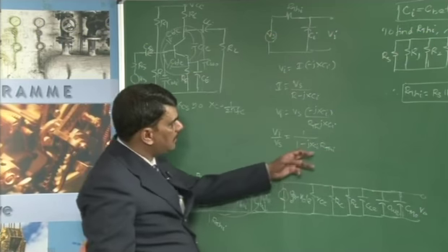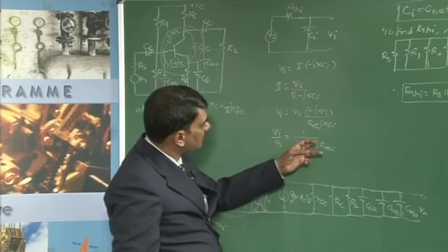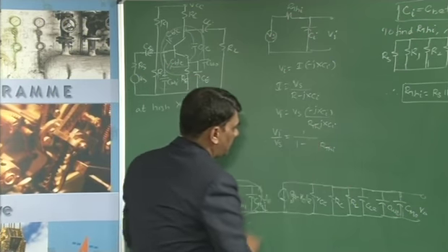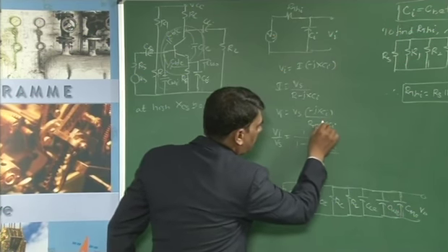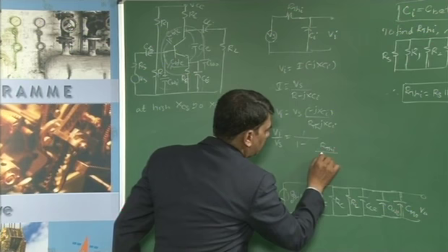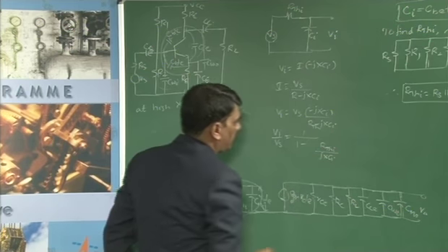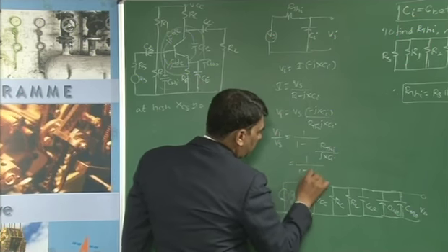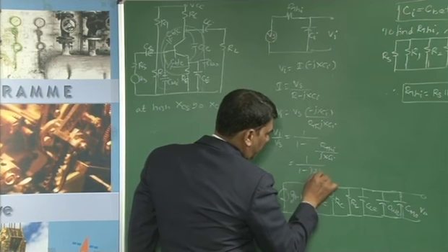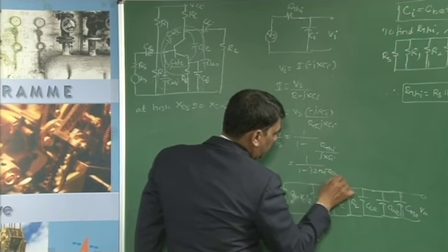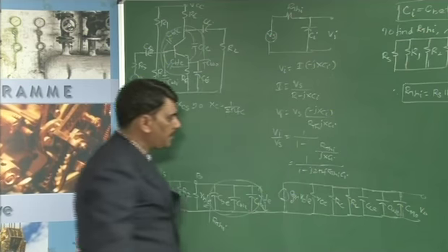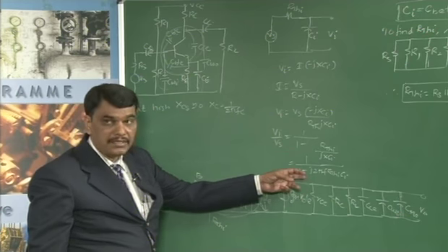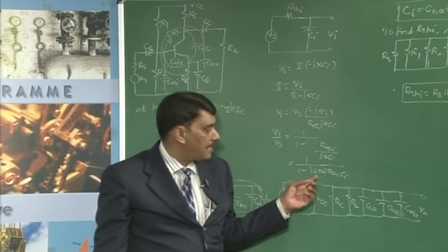If you divide by minus j, this becomes 1 minus jXci, so we need RTHI divided by that. Therefore, since Xci is equal to 1 by 2 pi f Ci, you are going to get 1 minus j 2 pi f RTHI Ci. If you observe, this gain is a complex quantity, therefore, we can calculate the magnitude and the phase.